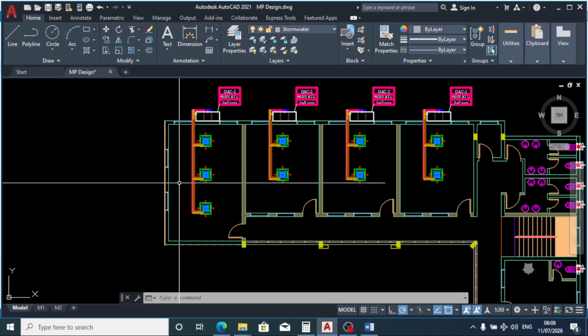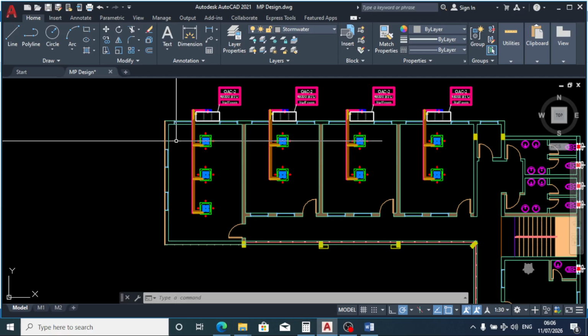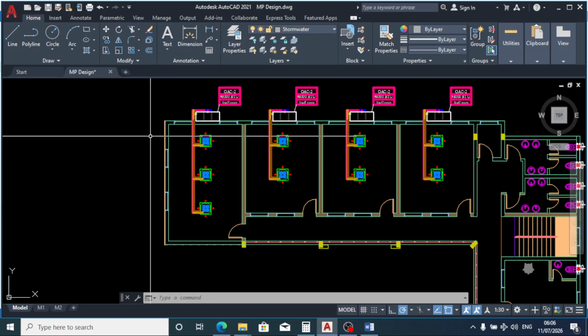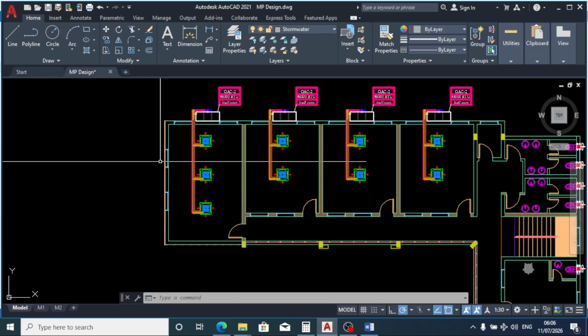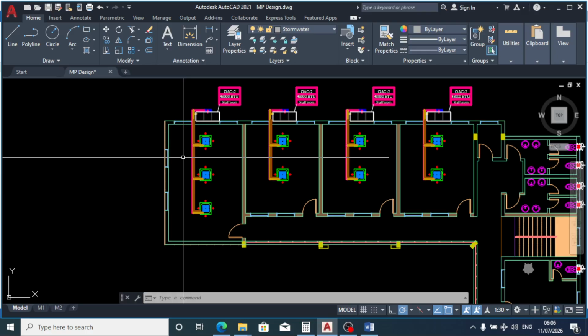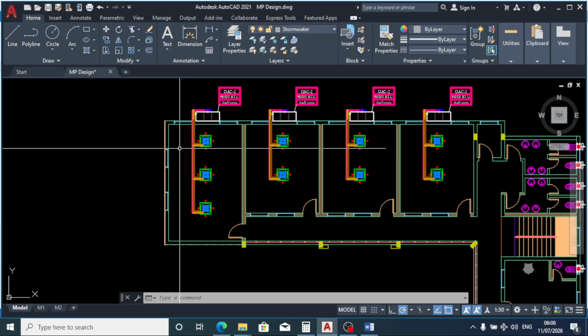We don't know the kind of paint the architect is proposing. We don't know if it's a heat resistant paint, because a heat resistant paint can reduce the conduction of the wall significantly, but since we don't know, in order not to undersize, we are just going to assume high. So let's assume 2.0 watt per meter squared Kelvin as the U factor for our wall.